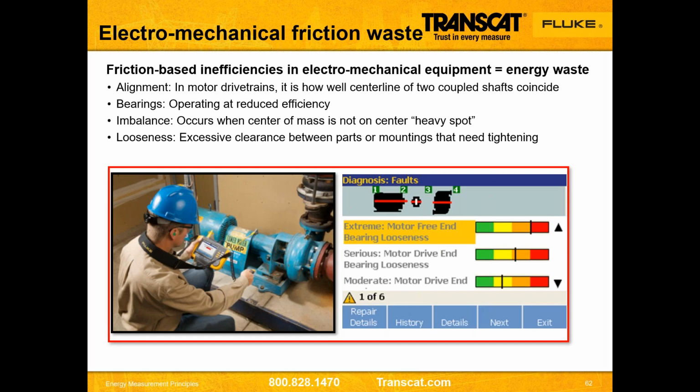And the analyzer at the end of this will tell us the level of vibration and where we are in the scheme of things in terms of how bad is it. Obviously, green being good and red being bad. So think about it being years, months, weeks, and days worth of time, and what I need to do about it. And that all happens in anywhere from under a minute to upwards of 10 minutes, depending on the complexity of that motor drivetrain.